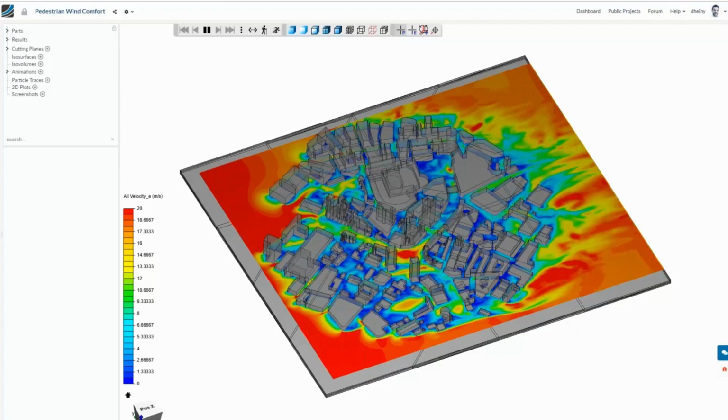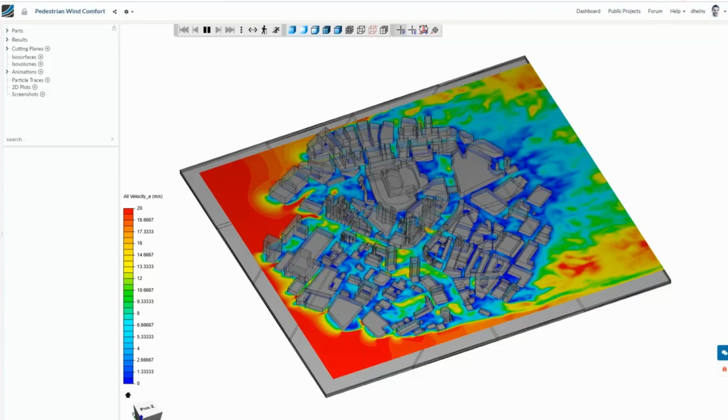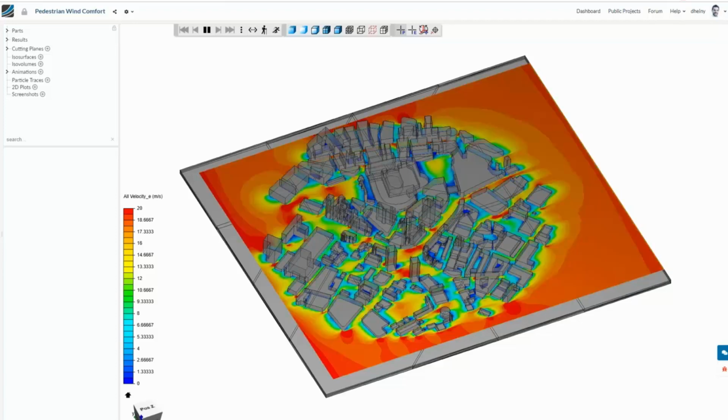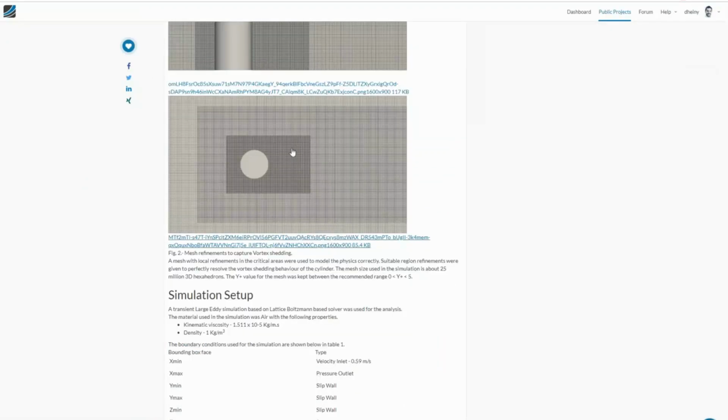One audience member asks whether or not the grid is uniform, or if I can bring in a finer mesh in a specific region. You can absolutely do that, right? Let's quickly take a look. This is available on SimScale. This is the cylinder project, where you can see that, driven by geometrical primitives around the geometry of interest, we drive different fineness levels, right? You can also drive that from the geometry. So you could say, for this specific building, I want to have a bunch of cells around it, inflated, so that I nail my Y plus, these sorts of things. So you can absolutely drive the mesh dependency.